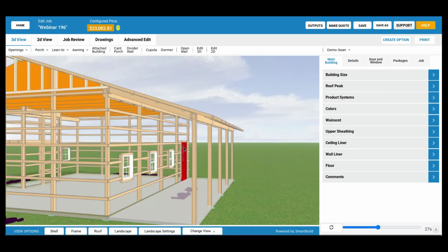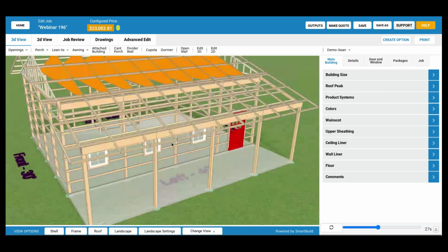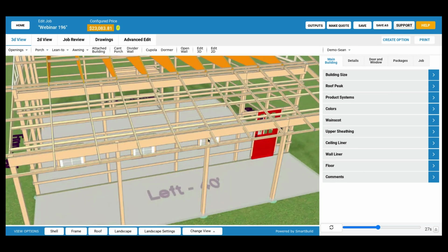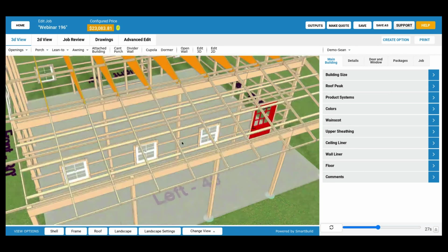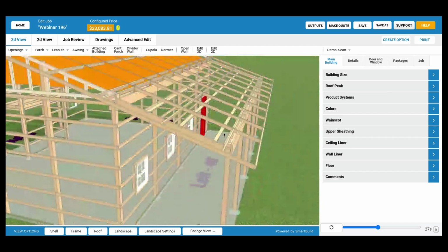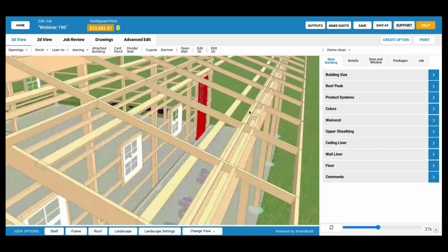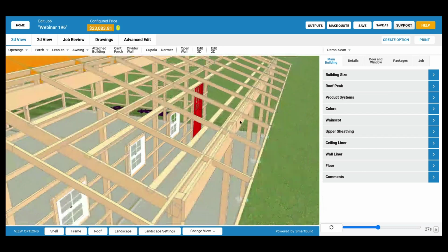Another one that I don't have actually demonstrated here, but if you do this kind of framing, you know, for outrigger framing, if you're using outriggers on the porch, we've just extended that outrigger up to the second purlin. It's always going to go up to the second purlin. Before, we could stop it at the first purlin, and you get into some situations where your outrigger wouldn't extend very far. It wasn't kind of feeding the bulldog, you could say, in terms of the structural support here.